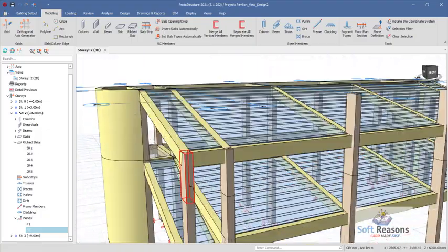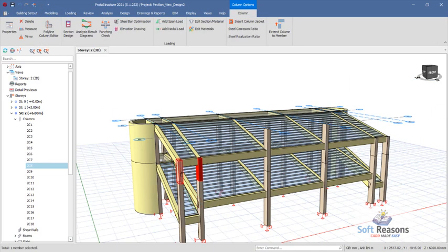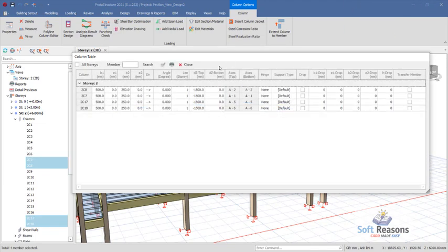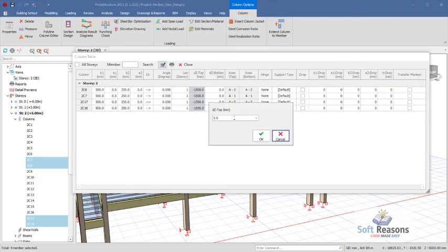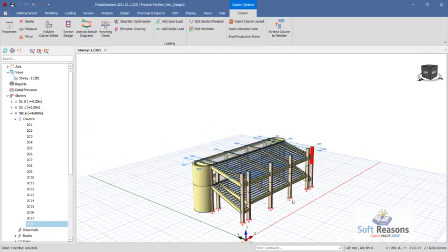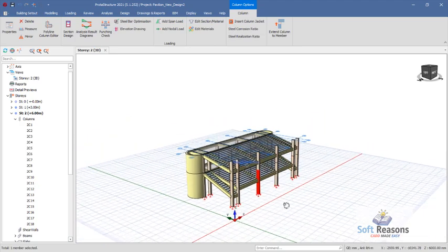For the columns, we have to remove the plane constraints. So select all of this column, or use the control key to have multiple of them selected successfully. Right click and then property, where you have DZ top, select that to remove the constraint of minus 1500, change it to 0. Successfully close this to have the columns, and then you have to check through these columns to make sure that it is not overlapping. Okay, so none of this is actually overlapping.